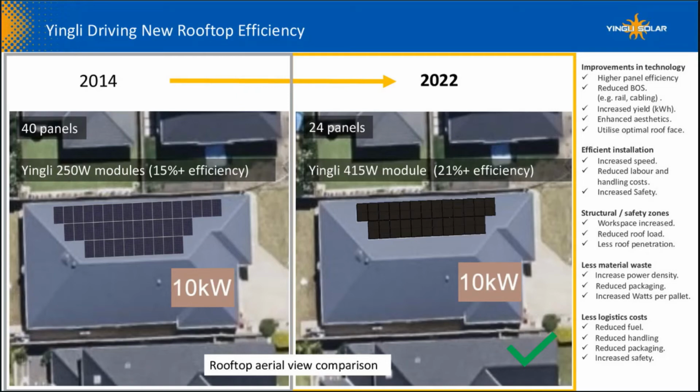Say you want to install an extra 1 kilowatt or more using the lower efficiency modules, you now need to utilize a less optimal roof side, and that side will generate less energy and increase system costs, because you'll need extra power conversion equipment in the form of optimizers or microinverters to better manage the now unbalanced electrical arrangement.